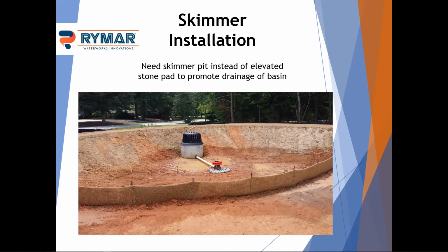It is typically shown on the plans that way, but often we see in the field it's not done that way, especially in areas where skimmers are new. Contractors aren't familiar with that. They find out after a few jobs that it's very hard to get grass established in the bottom of these basins, and they can become mosquito factories during the summer. So we do recommend to put the skimmer pit in to drain as much of that area as you can.